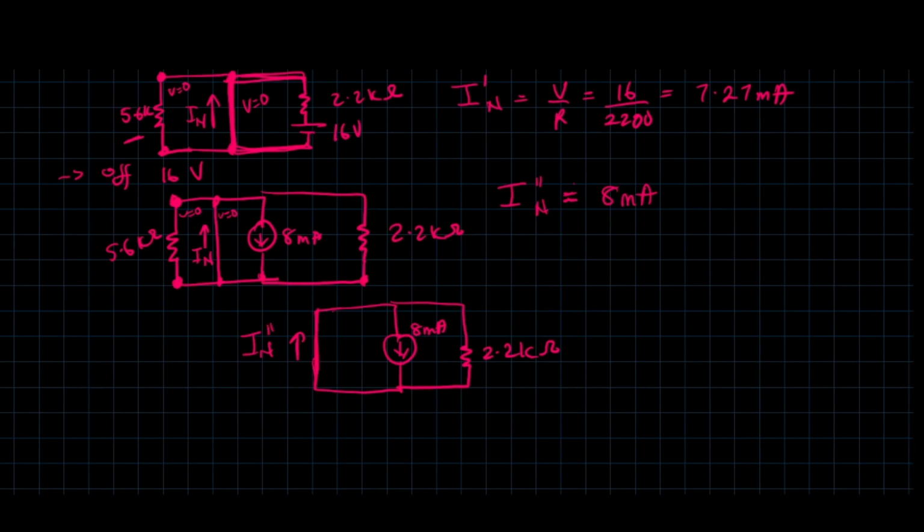Generally in a circuit, when you put only a wire there, current loves the place of least resistance. You see this place has a resistor, so it has a level of resistance, but this is just a wire. If the entire current would like to just come here, that's how you have, oh, my project has short circuited. So that's the thing about current. All the current will flow here. Nothing will actually want to go here. Nobody likes a hard life, to be fair. So I double prime N is simply going to be equal to 8 milliamps.